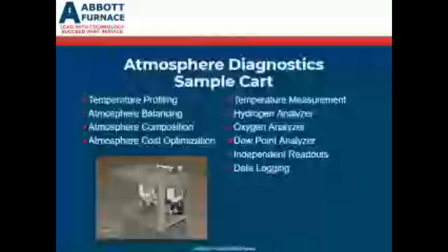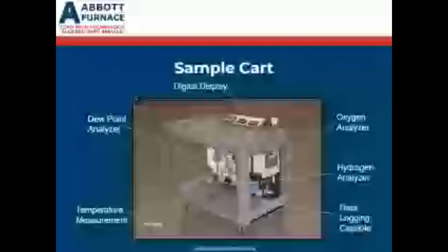Those will pick up any hydrogen or combustible gas that's working its way through a leak in a welded seam or a worn gasket, and we can do the repair to reduce the air leak. And again, we can add temperature monitoring and data logging to do the temperature measurement as well as the atmosphere analysis.